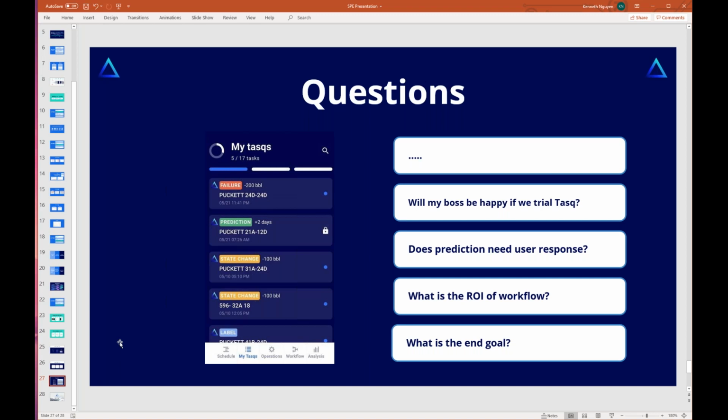Sorry, Ronnie, what was that last bit of that question? Are you able to what? Predict remaining operating time? Got it. Yes. So I would say definitely certain failures are a lot easier to predict because they're a little more gradual in their indicators. Scaling is a good example of this. You can definitely see this increase in temperature over a number of days. That is definitely something a little bit easier to indicate whether a failure is going to occur.